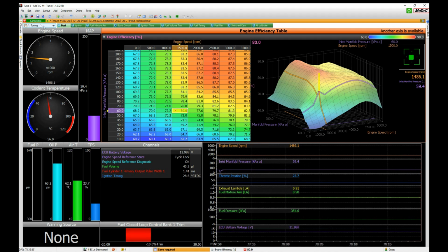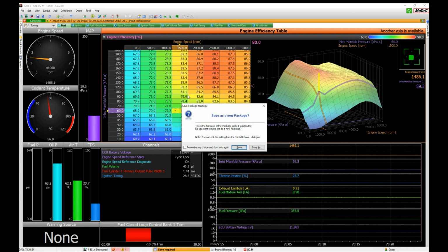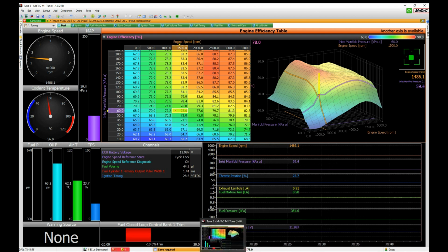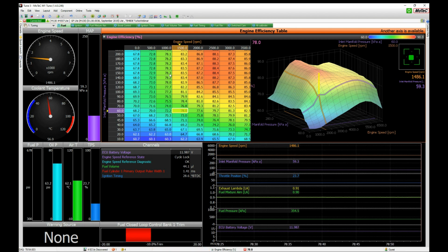So to save it, we can either click on the Windows Save icon, or push down Control S. Now the very first time I do this, because it's the first save I've made since I've opened Tune, it's going to do that. And the other thing that I didn't point out was there's a little diamond there that said that that site had been changed. So if we change it again, maybe I'll drop it to 78. So you see again, we've got save required coming down the bottom here, this going to orange and the diamond there. So I press Control S and it all goes away.